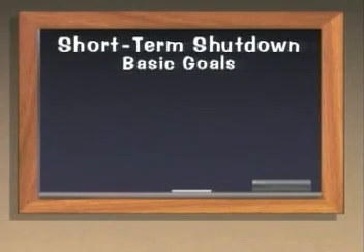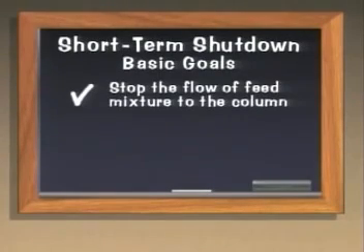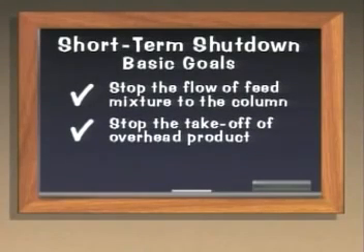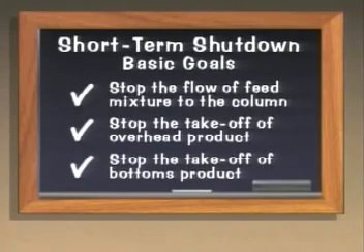The basic goals of a short-term shutdown are to stop the flow of feed mixture to the column, stop the takeoff of overhead product, and stop the takeoff of bottoms product.